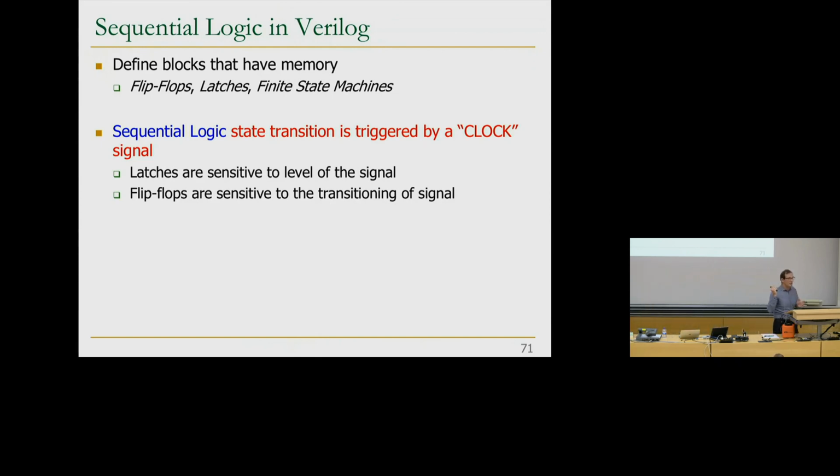Some things that I'm going to describe over here will be asynchronous, in the sense that some of the state transitions will happen maybe with some other input changes, not necessarily clock changes. That's a very different design. It's asynchronous design. That's not what we're going to do in the labs, but sometimes it could have its use also, because clock has some overhead, as we will see tomorrow. If you do asynchronous design, you can get rid of that overhead.